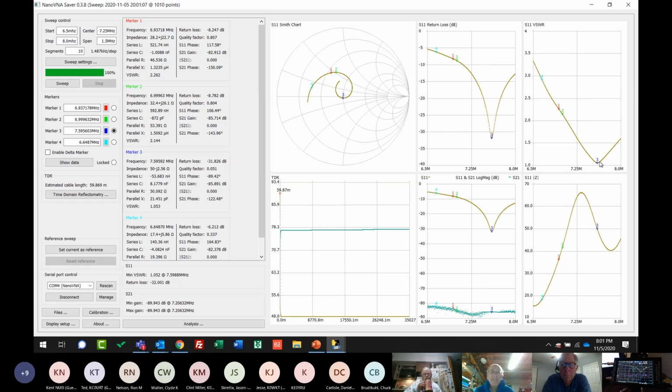You'll see that 0.3 here represents my 50 ohms and purely resistive load. The balance of the antenna over the range is very inductive, and so there's some options that I could perhaps use in there to add some capacitance and maybe bring that into better performance. So just an indication there of how we might use something like that.